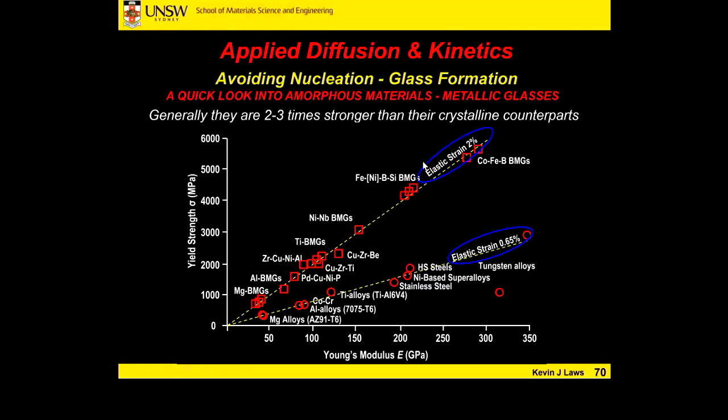They've also got this elastic strain limit of 2%. Again, that's due to structure, but hopefully you can appreciate something like a polymer, even an elastomer that's amorphous, or vitreous, usually has a very, very high elastic limit compared to a crystal.